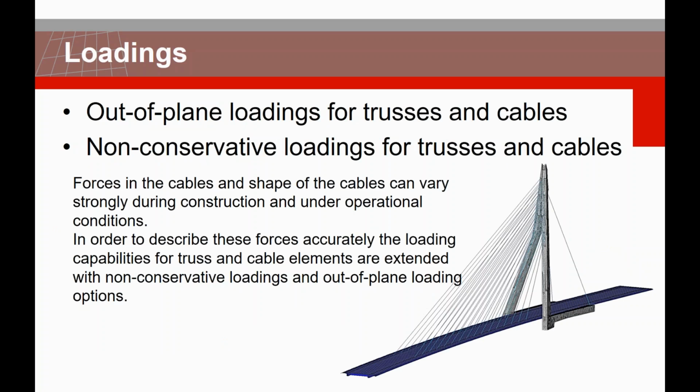Also, we have improved the position of the out-of-plane loading and also non-conservative loading for the trusses and cables, which are varying by the process of construction or loading process. So those information or loadings are basically getting adapted with respect to the position of the cables during the construction and changing the geometry.